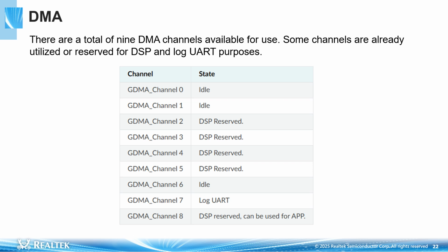For MP3 transmitter application, transmitter MP3 demo support, due to substantial audio data stream, the UART will dynamically request 2 channels. In the case of the transceiver application, transceiver demo support, SPI-TX dynamically requests 1 channel, while SPI-RX utilizes channel 8, which is reserved for DMA purposes.